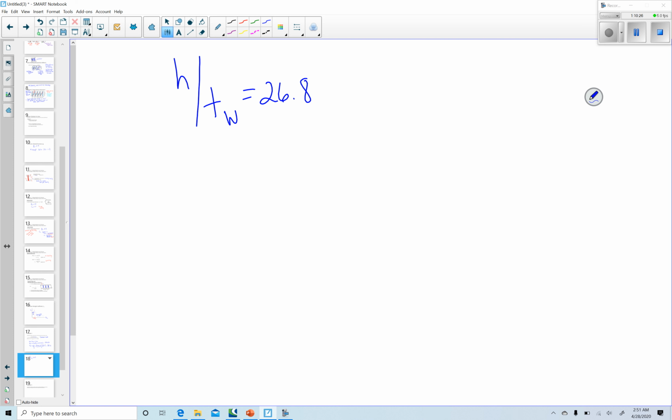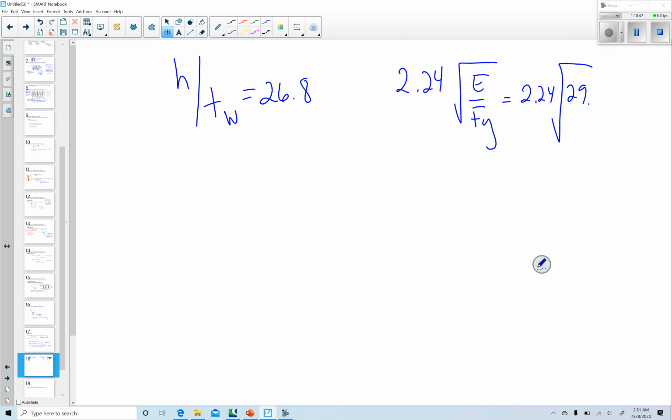Now I need to compare that to 2.24 square root of E over Fy. What, 29,000 ksi over 50 ksi.